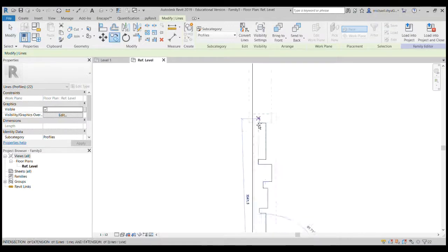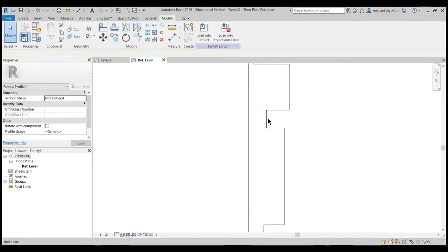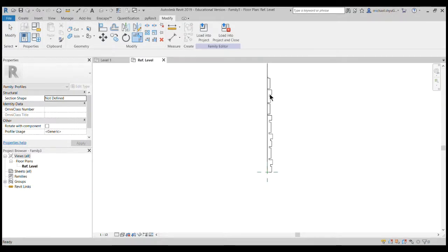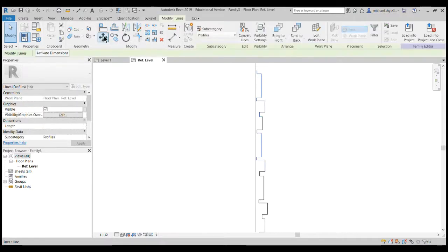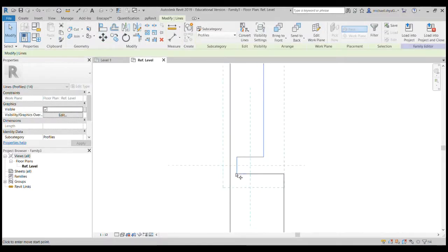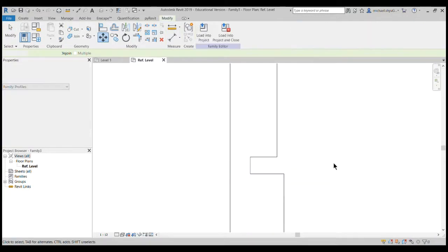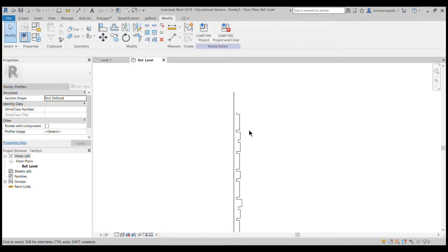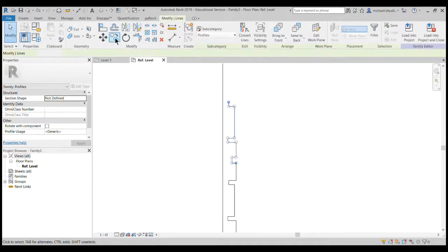Essentially, you need to clean these overlapping lines up and make sure that they are all connected. This is pretty important because this is generally why people have trouble with profiles and sweeps. I'm going to move this over just to make this a little more generous. But usually if your profile is failing, it's because the drawing is not clean.